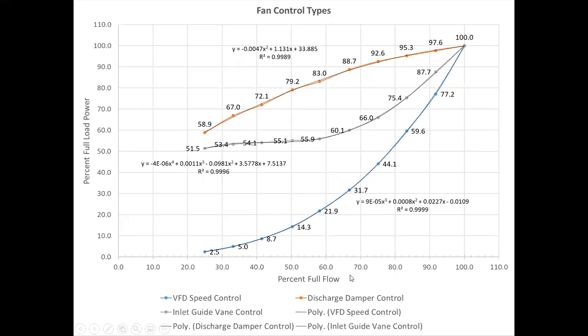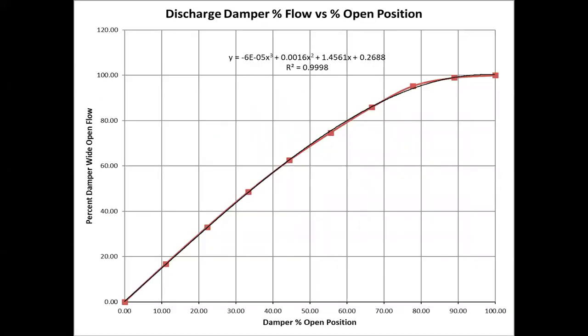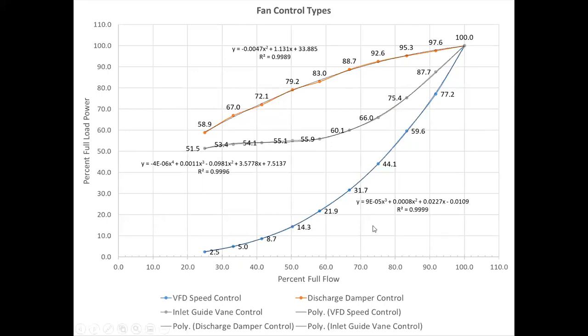And so if I know the percent full load flow, then I can use these curves to calculate the percent full load power, the change in power. And so you can use that to estimate what energy savings could be. Now, okay, let me go back. Notice this is percent full load flow.